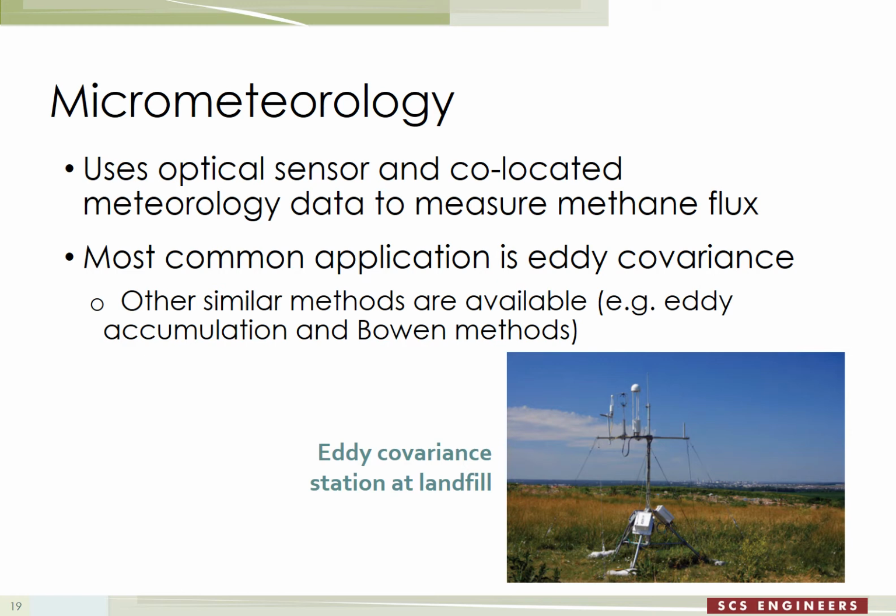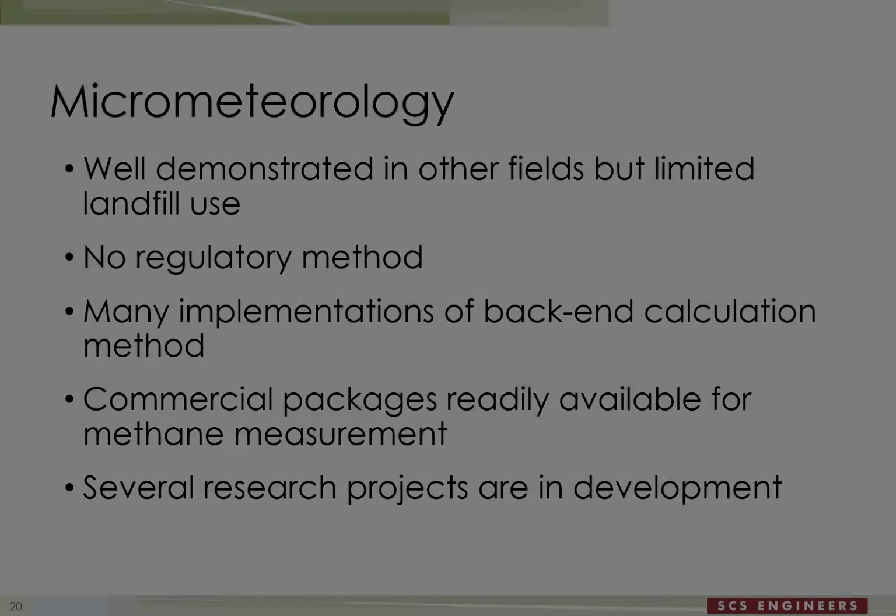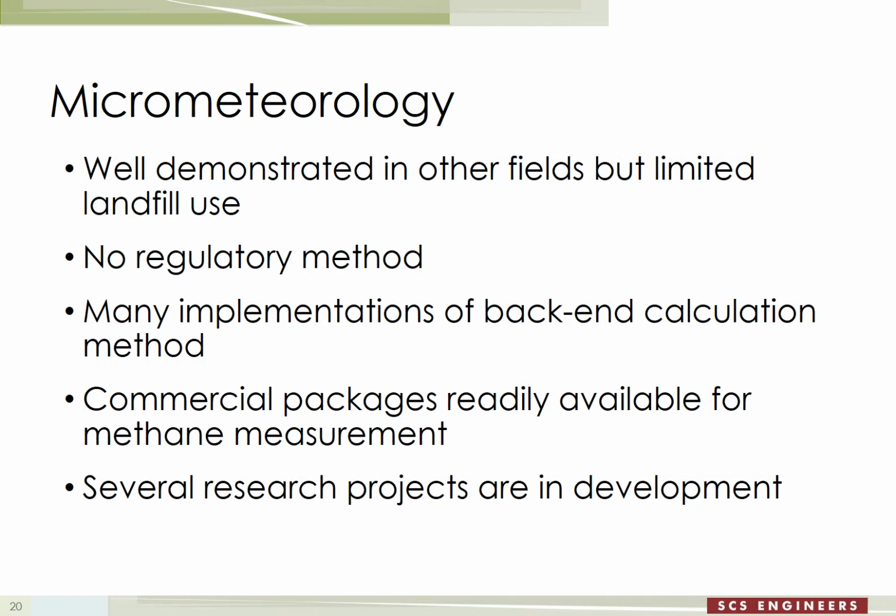Eddy covariance is a common one of those and has been used at different landfills. But again, they don't have a lot of field use, particularly on landfills. There's no regulatory method that's been approved for it. Of course, they still use those back-end algorithms to calculate emissions, and that produces some degree of uncertainty.